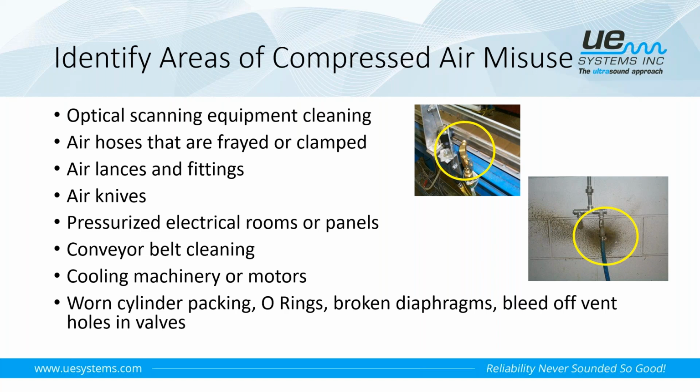Cooling machinery or motors, to some of us, it may sound horrible, but you'd be surprised at how many times I've been out in plants and facilities and seen that. Worn cylinder packing, O-rings, broken diaphragms, bleed off vents. A lot of times too, telltale signs are going to be like the dust collectors, as I call them, where you've got leaks. Your compressed air is going to have moisture. It's going to have oils in it. So over time, those leaks become dust collectors. So those are, again, telltale signs of leaks.